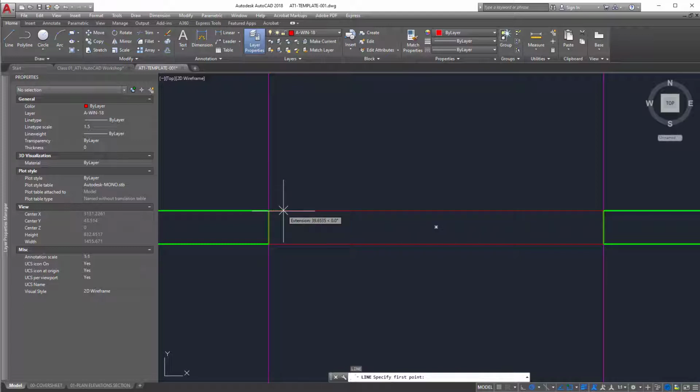And you can see there's a tiny little green dash line that appears, and it says extension and then a number. I haven't actually drawn anything, but I'm moving my hand off of that corner, and I can type in a start point for this next line because I am just drawing a single line now. So I'll type in 50 and hit enter. Now what that means is it's going to start 50 mil away from that point that I was hovering over before. So I'm going to draw down, hit escape, that's now complete.